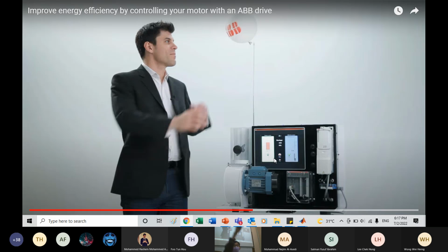In industry, all these things we call AHU, air handling units. Including our Block A, I can see they are still not using variable speed. They're using dampers. The moment I turn on the aircon, even if we put the fan very low, we are still taking the maximum power. So this is what happens right now. In the old days, that's the design. And then people feel that variable speed drives are expensive. I want to buy a lot, but they don't want to spend this money. Then you'll see what happened.